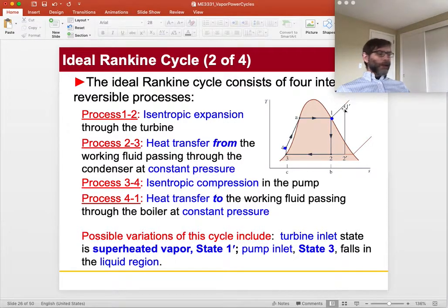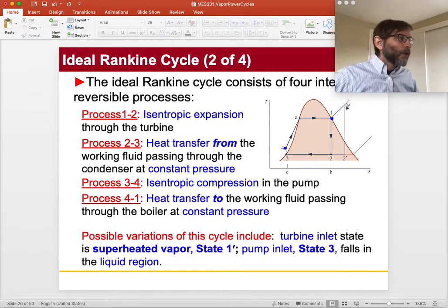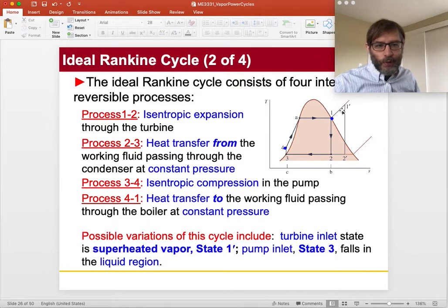We're going to talk about the relative advantage of having it inside or outside. Meaning, if we add what's called a superheater and superheat the steam beyond the saturated vapor point, then we go to 1, 2, and this is where we expand down to some low pressure. Then we have to reclaim the water and make it into water, and this is where the condenser falls out.